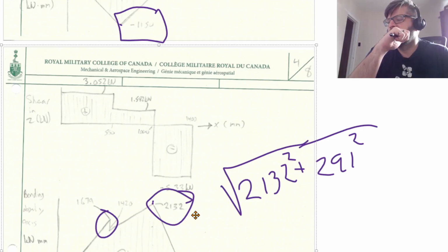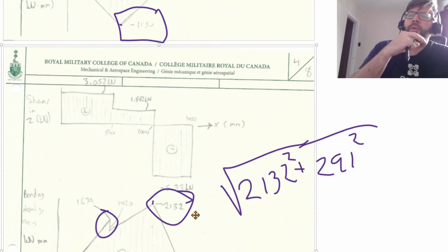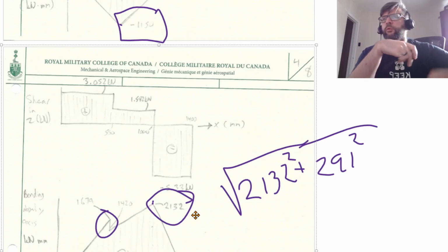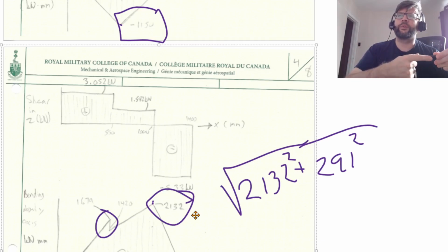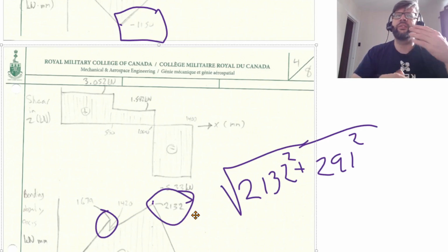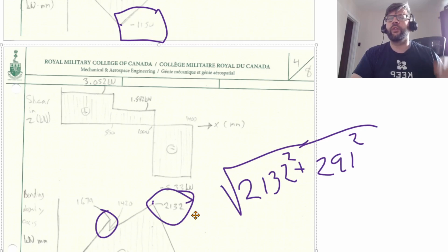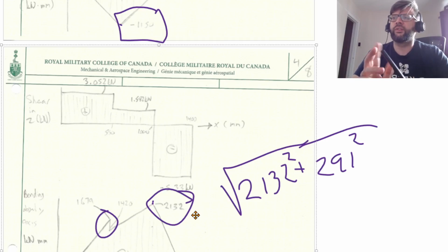We're more so worried about what the magnitude is, because the magnitude is what causes the stress, and the stress causes cracking. We're rotating the shaft around, and the point where the maximum stress occurs is a point in space. So as we rotate the shaft around, points on the shaft are going up and down to that amount. So the stress occurring due to this is completely fluctuating. The fact that we have the maximum stress at a particular point in space doesn't really tell us anything about the shaft itself, so we don't really care.